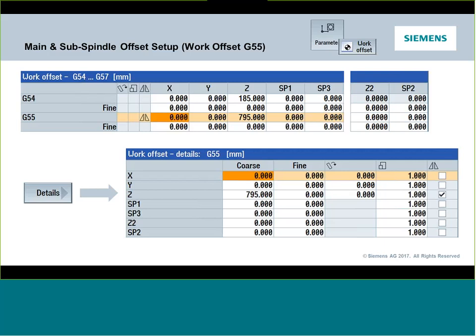And what that's saying is whenever G55 is called up, my Z is going to be mirrored, or pointing in the opposite direction. So any motion towards my part, anything that's cutting into my part, is always going to be a negative value. The physical motion is going to switch, but it's always going to be a negative direction when I'm moving towards the part. The beauty of this scenario is I don't have to keep thinking in my head which of the two spindles I am working on as far as which direction I'm telling my Z to go. That's always a challenge when I don't have the ability of mirroring the axis. I've got to always remember, okay, I'm on the sub spindle, so I've got to be moving plus while I'm turning or drilling my part, or on the main, I've got to be moving minus.